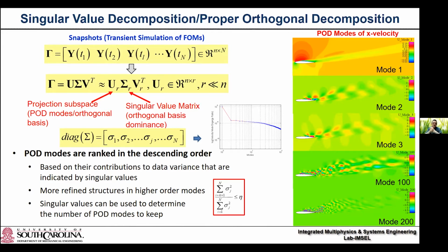So basically, we know that when we run CFD or finite element simulation, you will have a 2D or 3D solution. After you do this calculation, all you need to do is, regardless of 2D or 3D, unfold all the solutions and make them a single column vector. In other words, I don't care whether this is 2D or 3D, but eventually, after you get this solution, you will make it a single column vector.